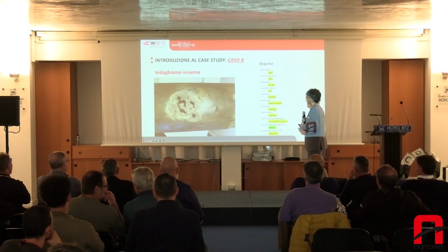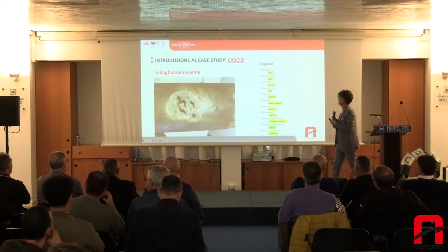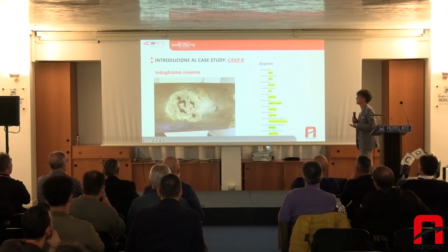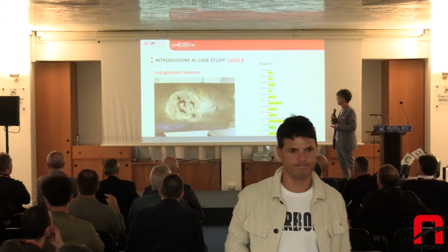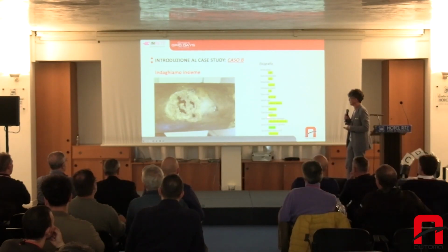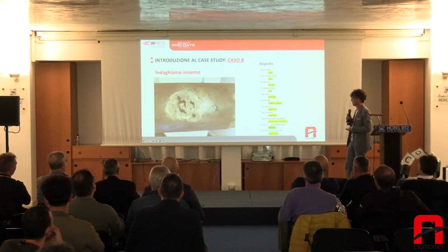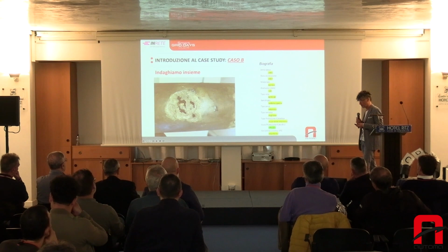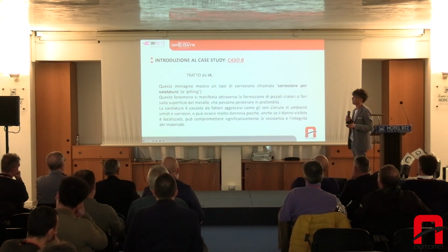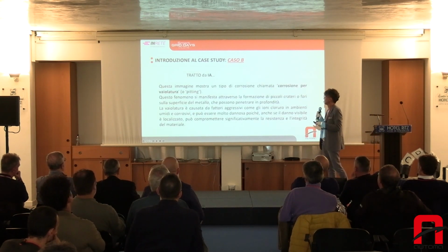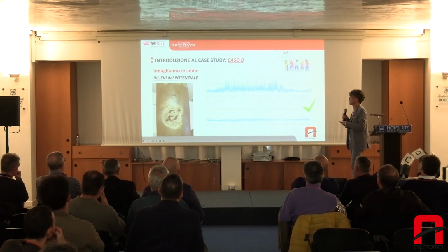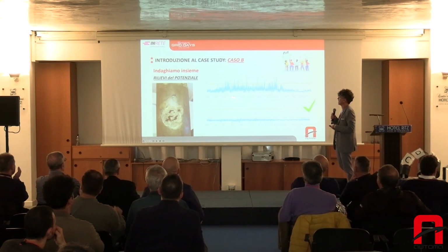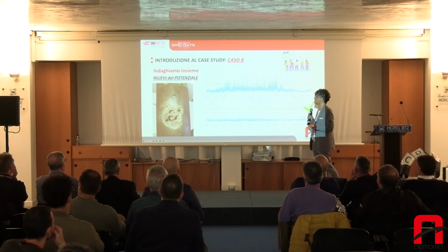Case B. Then second case, B case. That was laid in 1991. The pipe was no longer used in 2007. The type of cathodic protection is always the one we had before, and there were interferences. Here too, sending the picture to artificial intelligence, this is what we get from the artificial intelligence system. We have corrosion by pitting.